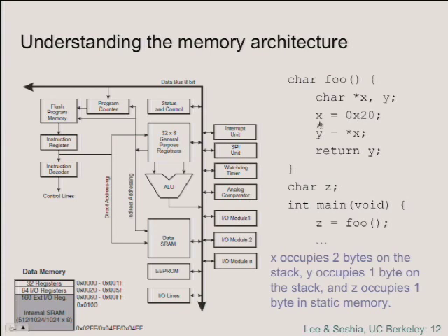Y will get the value of the memory location 0x20, which in this architecture is simply the first of the 64 I/O registers. So if you have an external device that you've built, you've wired up some piece of hardware, and you'd like to convey to your program some information from this external device, one way you could set this up is simply hang your device off the bus in such a way that when the address 0x20 appears on the bus, it asserts your value on the data lines, and bingo, your C program can read that value and assign it to a variable and operate on it.